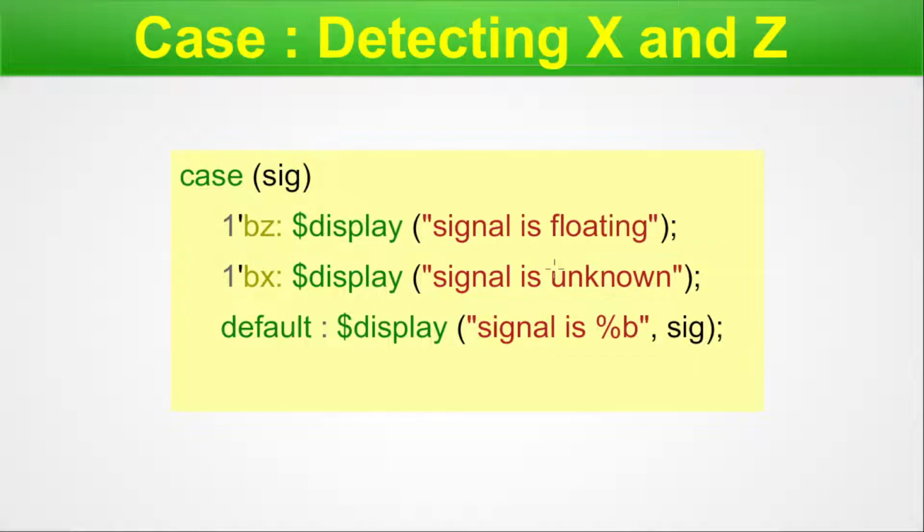Let me clear the markings. If this is more than 1 bit, it has some width. So here you can modify accordingly. Here we have the end case, and this ends the case statement. It's simple, yet it is very important for the interview. So you are done with this example. So let's move on to the next slide.